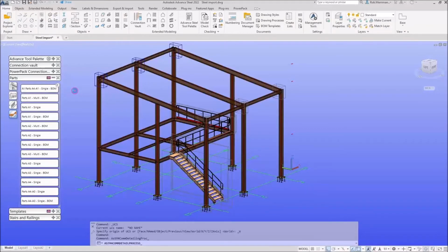A4 to A1 is these sheet sizes. How Advanced Steel works is it asks, can I fit the plate onto a fab drawing, and can I fit it at 1:1 scale, yes or no? If it can't, it'll then go to 1:2 scale, then 1:5, then 1:7.5, 1:10, 1:15. When it gets to 1:15, it says, okay, I can't fit it on an A4 sheet. So then it'll try an A3 sheet, go through the scales, then an A2 sheet, then an A1 sheet.